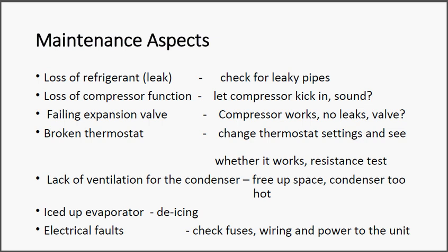Loss of compressor function, so your compressor might go down. There might be several reasons for it. One might be just electrical, that there's a fault in the supply. So first of all, I would check the wiring for the compressor, make sure that power is fed to the compressor. You can normally hear it as well on a fridge, when the thing runs, whether the compressor kicks in or not. So it's one way to find out what's going wrong.